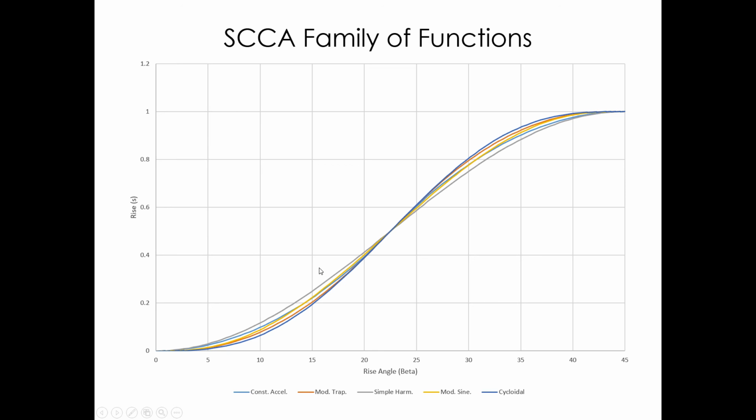I mean, you can usually look at a cam and tell if it's bad, if it's just got like right angles and stuff in it and hard corners. But for something that's halfway decent, you can't just look at it and tell what these are. You'd have to actually measure the height in different places and plot it and then do the derivatives, which is a really noisy process. So it's really hard to actually reverse engineer a cam because the position doesn't change very much for these functions. I mean, this is really the maximum difference between simple harmonic and cycloidal. It's just there's not a lot of variation in there, right? You know, you might be talking just a few % change in the position. So you'd have to measure this very, very accurately.